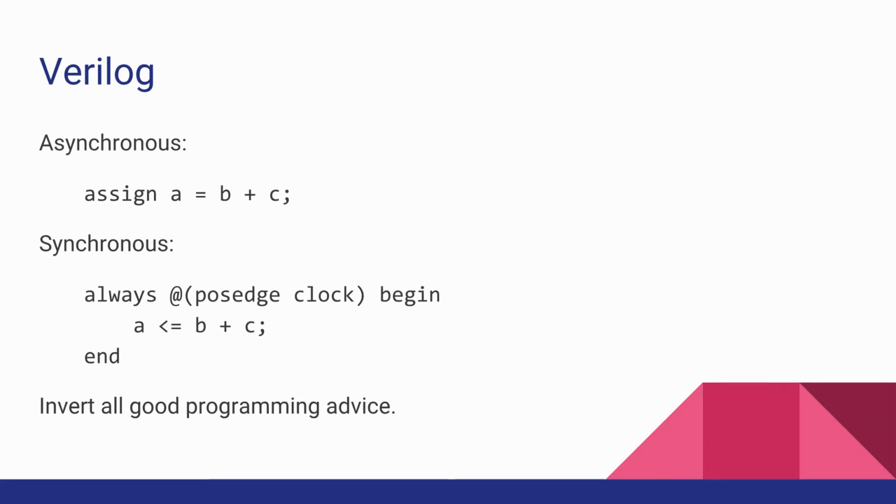A will change. So does that mean, I can't remember how many, so for adding, is there any support hardware there, or is it just straight from logical elements? So for the adding, it would be the straight logical element. Each one has, let's say, usually a 1-bit adder. So for this, you might use 8 of them because it's a full adder, so it's got a carry. You would instantiate 8 of them and then hook up the carry across them, and you would do the B and the C, and then whatever the output is comes as A.